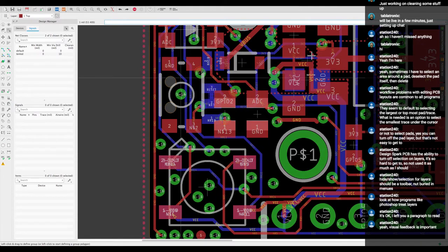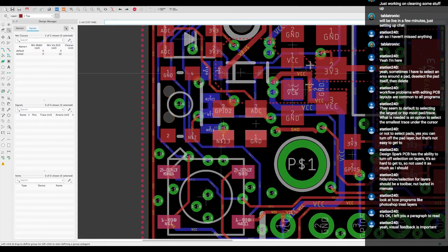But the reset buttons pull side to side. They short side to side, and then they have a mounting bracket on the front that solders. That's not electrically connected. So I added this little jumper right here to pull this pad down to ground, so that if you hook that switch up that's side mounted, you can use a switch that goes side to side or front to back by jumping that out.